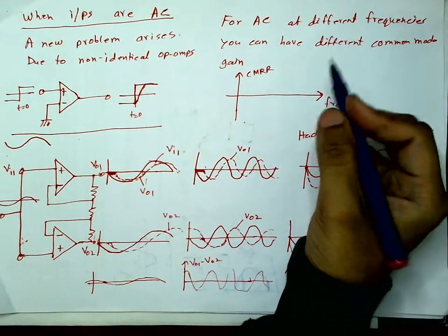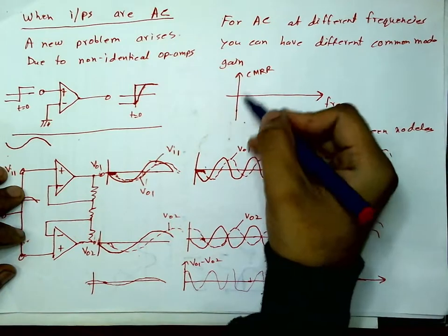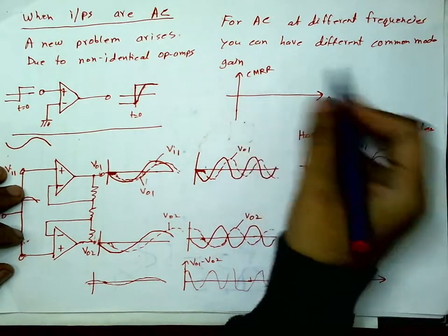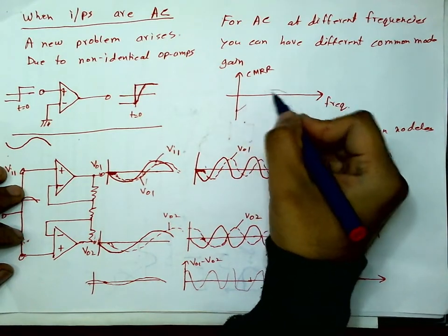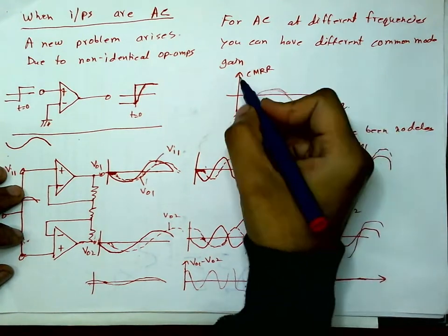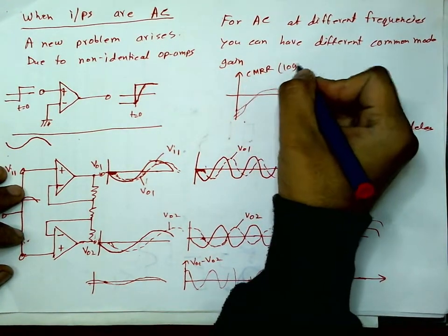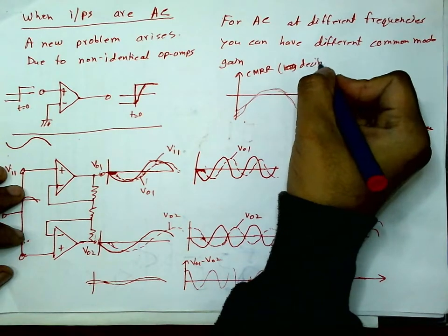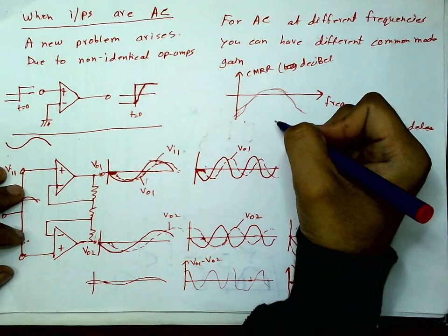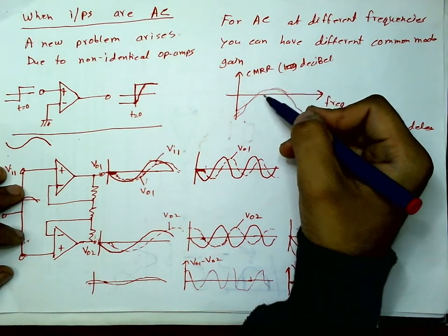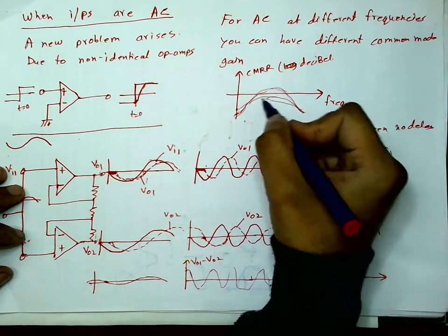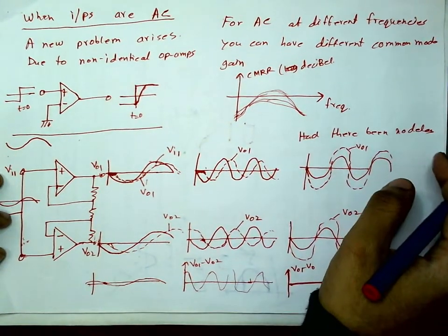Generally in previous years we have found that this common mode rejection ratio increases and then decreases again. Ideally this should be in log domain. If it is in log domain or in decibel, this should be minus infinite. Okay, common mode gain should be 0, so log of that should be minus infinite, but we find it increasing and decreasing, so that you have to do.